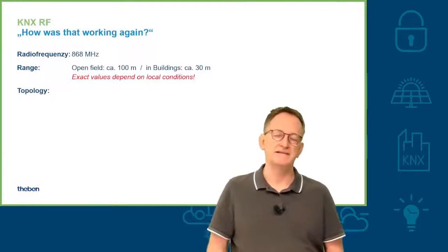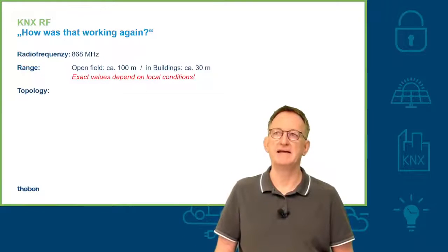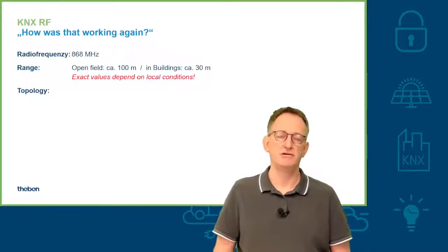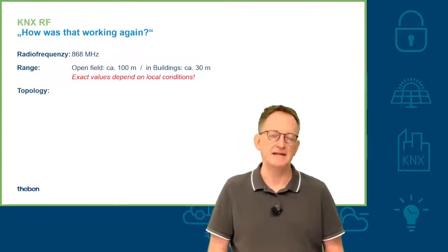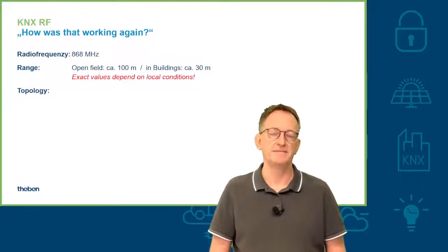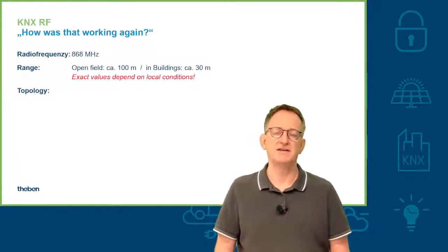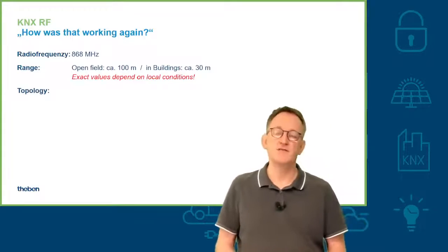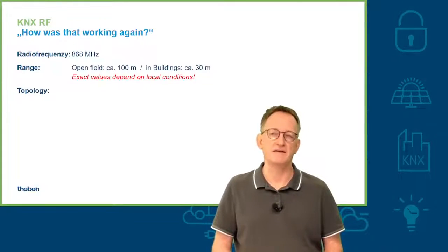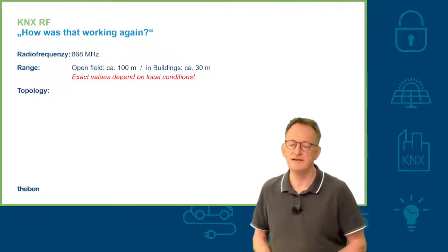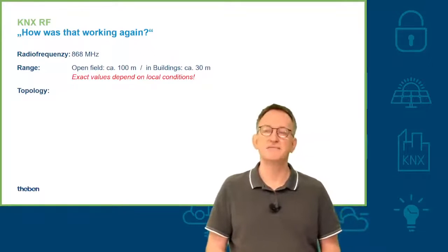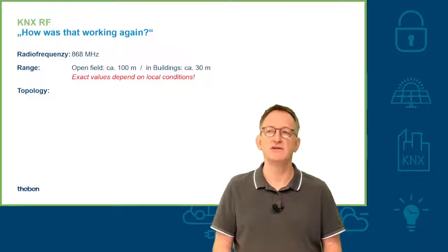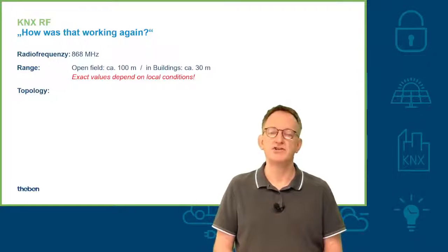So what is the general technique behind KNX RF? We are using a radio frequency of 868 megahertz. Unfortunately, this frequency is not reserved just for KNX communication. It is also used for many other systems and purposes. So we are really sharing that frequency, and the other systems might also have an impact on the quality of the transmission of the data.